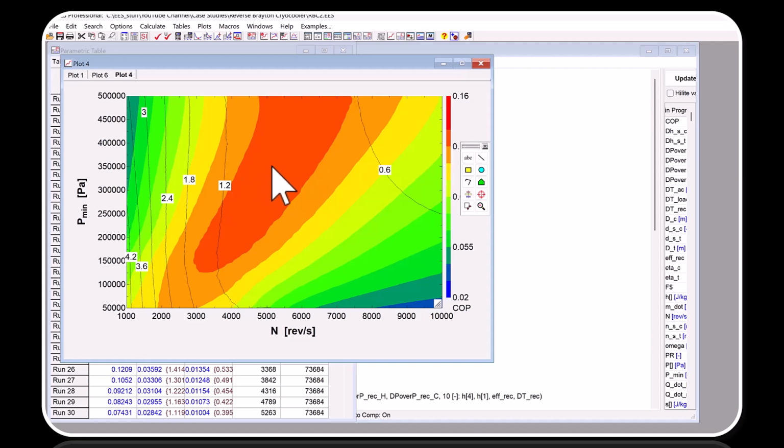diameter. So I don't know, it looks to me like if I want to make my turbomachinery as large as possible, I'm going to be wanting to be down here where the compressor gets to be maybe 1.3 or 1.4 inches versus up here where it's maybe only 3/4 of an inch. So a bigger compressor that's running more slowly is going to be a little easier to make, and I can do that if I go to lower pressure and lower speed.